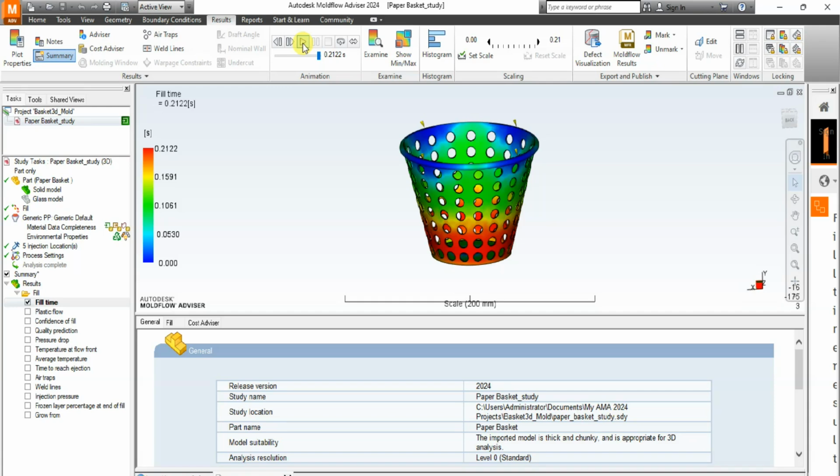So in summary, a short shot is the incomplete filling of a mold part, resulting in an incomplete part or defect in the end product. The major characteristic of a short shot is that it has translucency, that gray attribute, to show that there's something missing there. It's obvious in the simulation, but in this case, as you can see, the flow is perfectly in order. The colors are very, very clear indicators of a smooth production with high confidence. Now let's talk, still on the fill time.